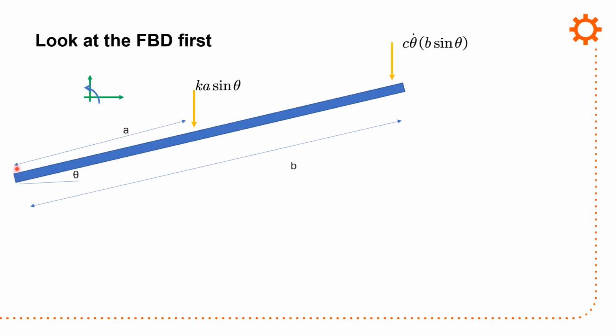So again, all you do in every one of these problems is the same thing. You set it up so you end up with positive rotations and positive moments. I'm going to solve this as a moment question. That's something you should immediately recognize, and the reason why it's a moment is because it's pivoting about this point. I have the spring force, which is acting in opposition to the displacement. It's going to be pushing down. I have the damper force, which is acting opposite to displacement. I have the distances B and A, which I'm given here. These are the positive directions, and counterclockwise is positive.